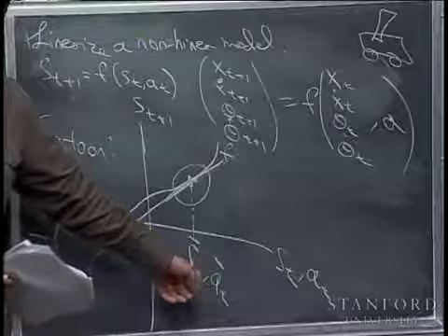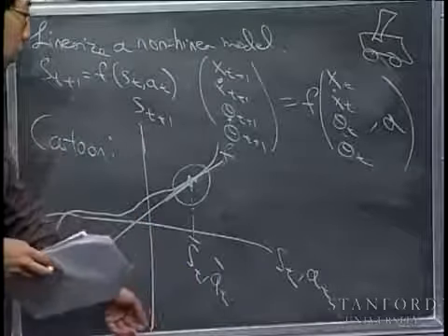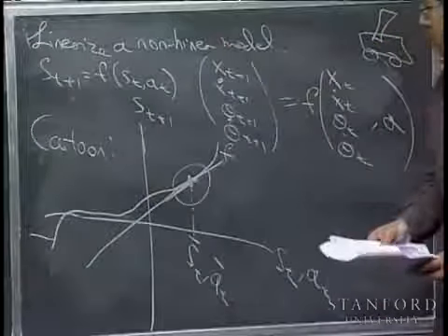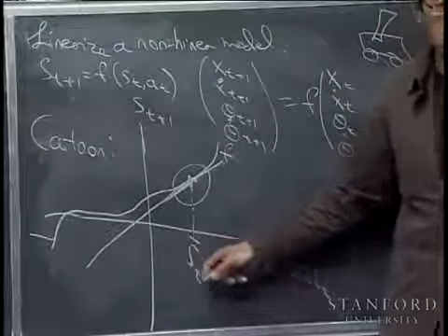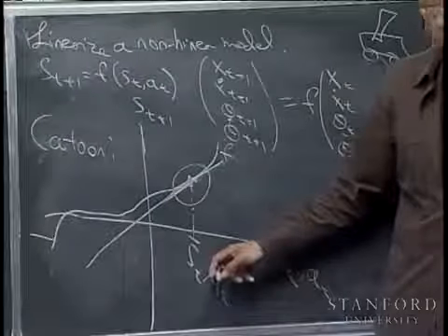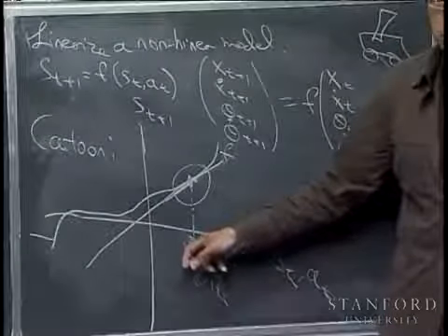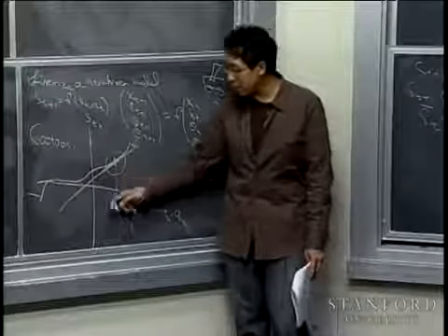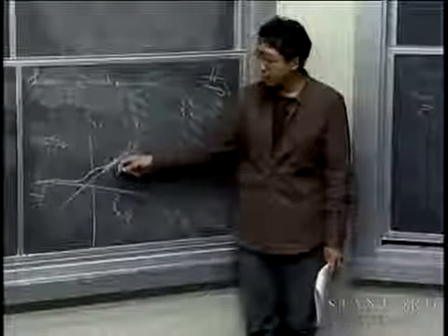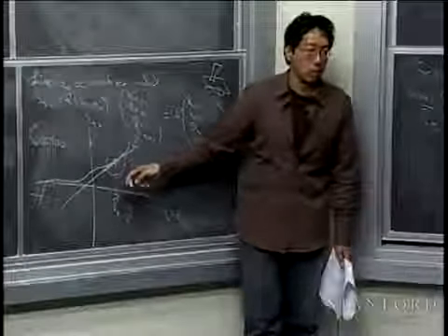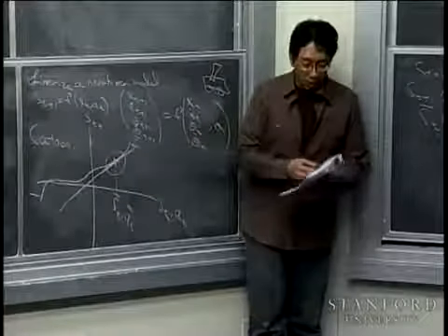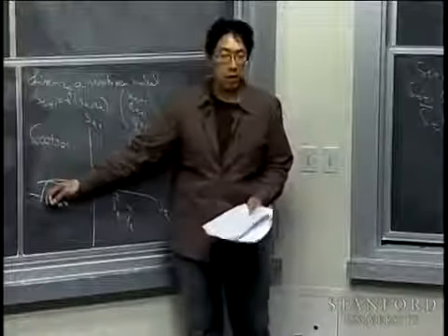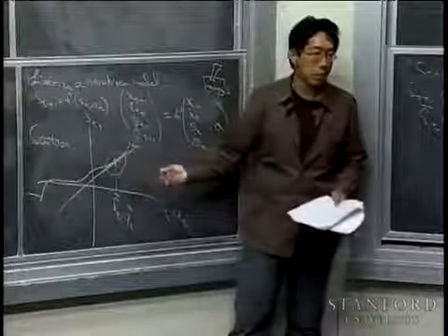If you expect your inverted pendulum system to spend most of its time in the vicinity of this state, then it'd be reasonable to linearize around this state, because the linear approximation will be a good approximation for the states where you expect the system to spend most of its time. Conversely, if you expect the system to spend most of its time at states far to the left, then this would be a terrible location to linearize.